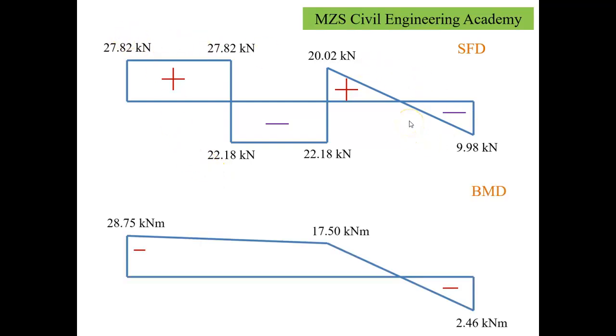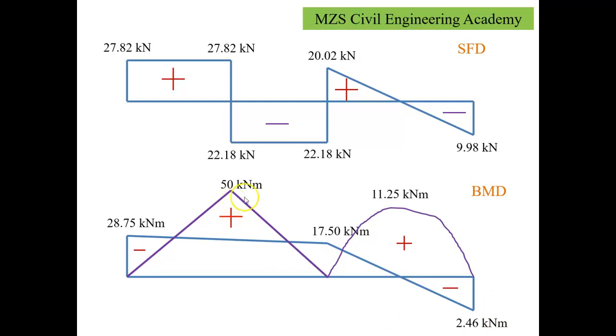Similarly, we can draw the bending moment diagram, which shows the distribution of the moments which we have received after the solution of the slope deflection equations. So this is the final moment at end A. This one is the moment at end B, and this one is the moment at C. If I want to get the net effect here, I have to overlap this with a free moment diagram, which we can obtain for the individual span based on the loading condition.